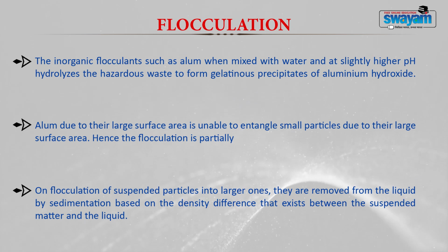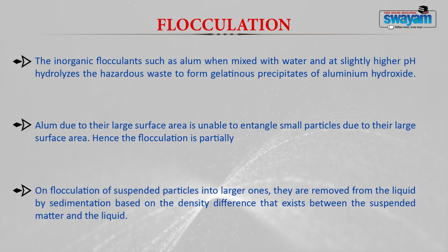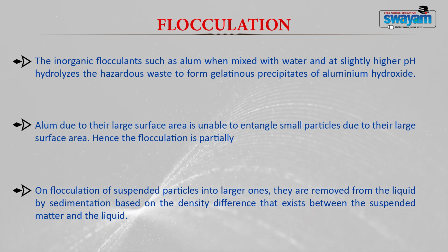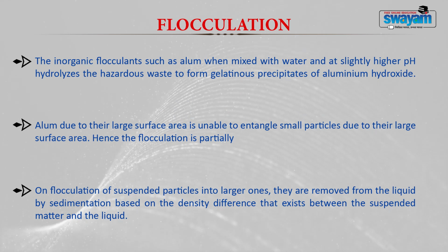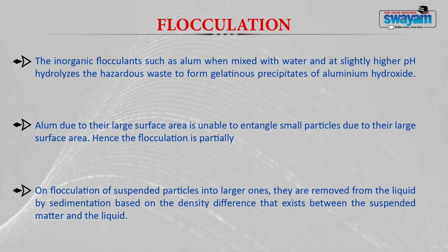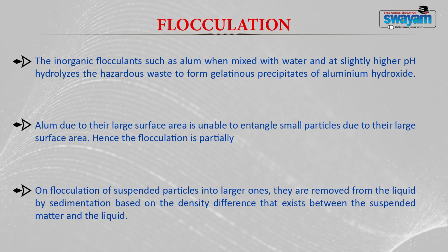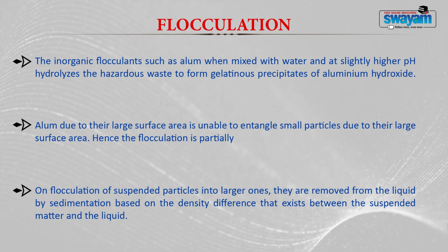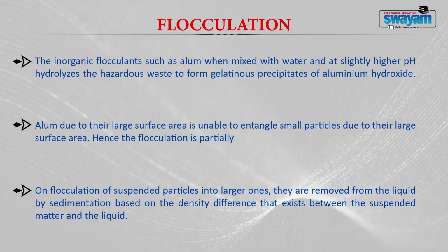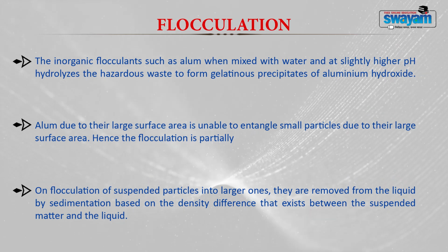Now, on flocculation of these suspended particles into larger ones, you allow them to settle down, and the flocculated suspended particles will be removed by the sedimentation process. Generally, the separation takes place based on the density difference that exists between the suspended matter and the liquid.